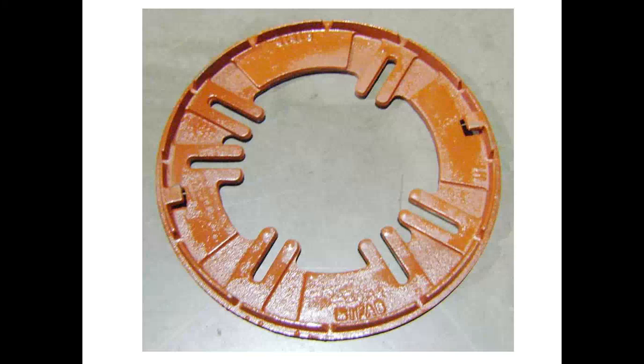This is really applicable where a roofer says, I'm doing a re-roof, I'm up there on the roof, and the clamp ring is broken or rusted or corroded. It's 30 years up there. I can get that off, but I really don't want to dig out the body because it's cast in concrete, or the body's fine, it's in place. I don't want to touch that and disturb the membrane up there. So in that event, just clear off the old membrane clamp. It may be gone already. Bolt this to the top of whatever body you've got, put our dome on, and away you go.